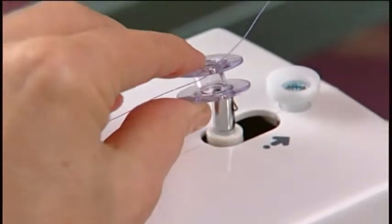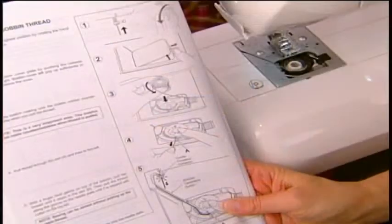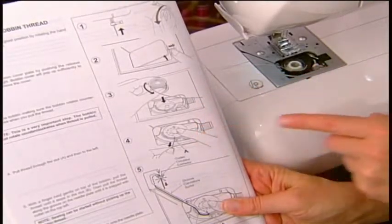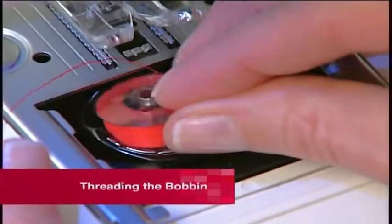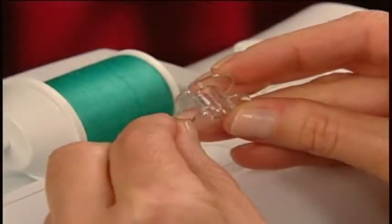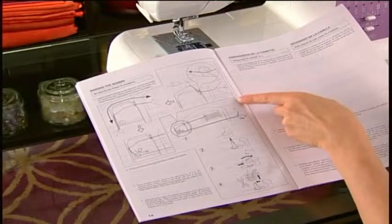In this part of the program, we'll give you some suggestions that will help you thread your machine properly. By following some simple guidelines, you'll find it easy to get your machine ready to sew. The machine bobbin is threaded before the upper part of the machine is threaded. Machines vary from model to model with regard to the bobbin winding and threading process, so check your machine manual for the correct procedure on your machine.